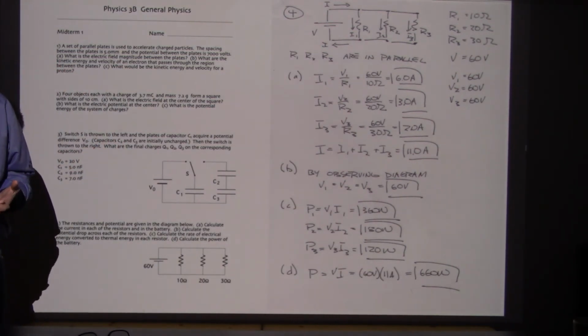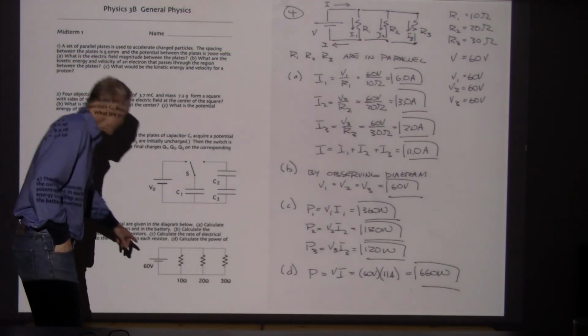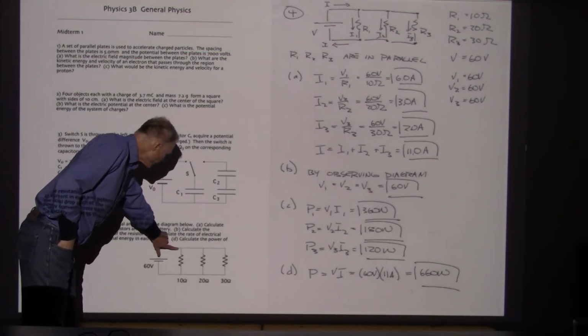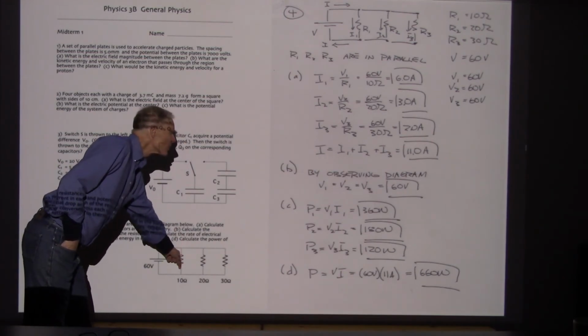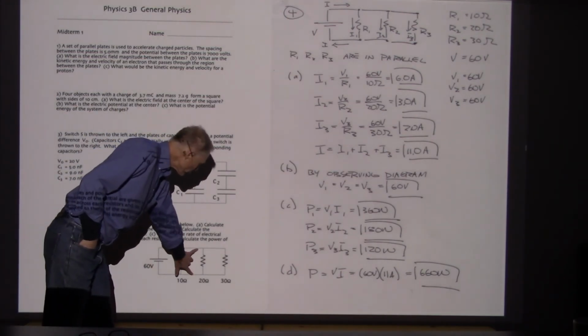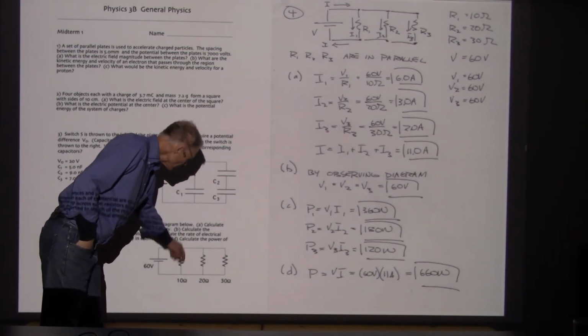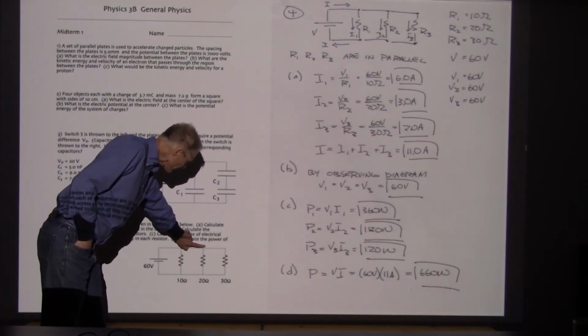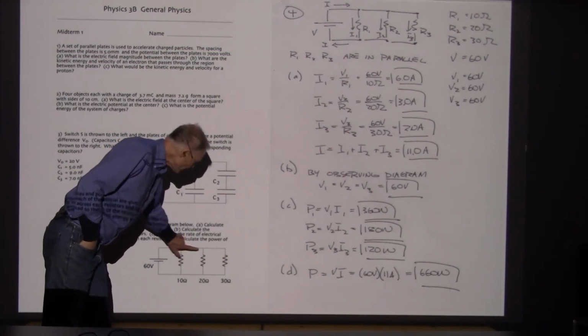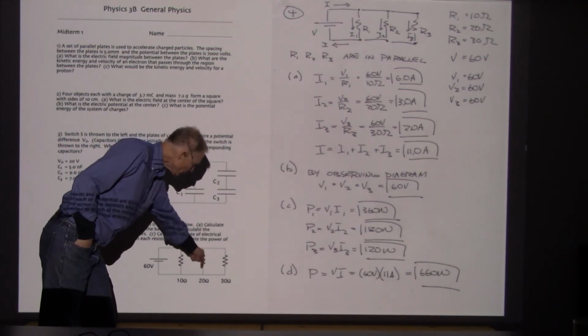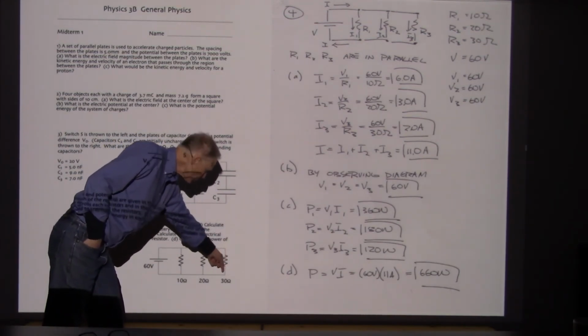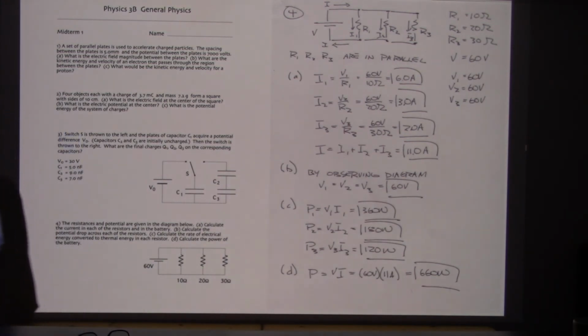That's got to be at 11 amps. So there's 11 amps of current flow here. And then this is 6 of that. So how much current would there be here? Here and here. 6 has gone this way. This would be 5. And this would be 5 here. And then here the 5 splits. 3 goes through here. And 2 goes through here. So, yeah, you should be able to identify the current in each section of that circuit. So any questions on that, let me know.